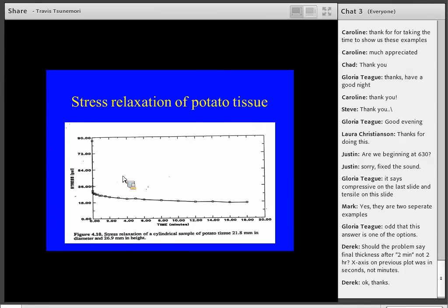We can have a similar process as stress is applied, a known force is applied, or a known compression is applied. So if we squeeze something a certain amount and then stop squeezing it, we just sort of leave it there, it will slowly adjust to that. Lots of biomaterials, lots of these viscoelastic materials will adjust, and the stress slowly reduces.